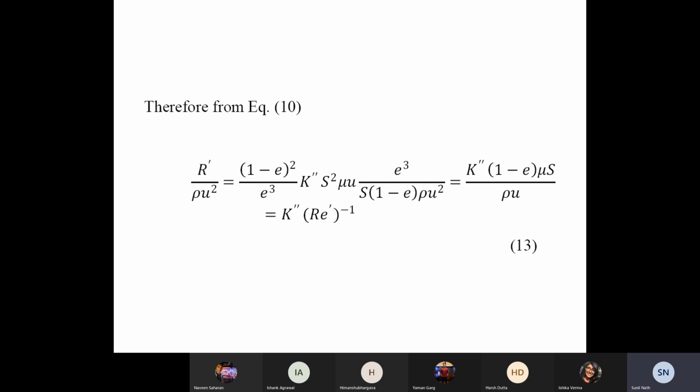And then if the flow were to become completely turbulent, which probably doesn't happen until Reynolds number is very high, beyond a couple thousand, then that slope goes from -1/4 to 0. Okay.